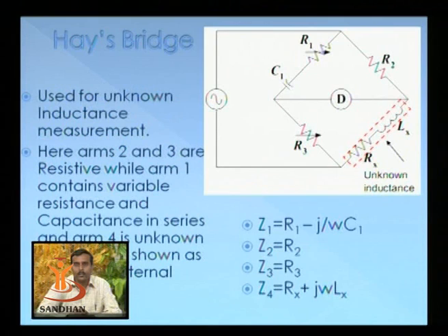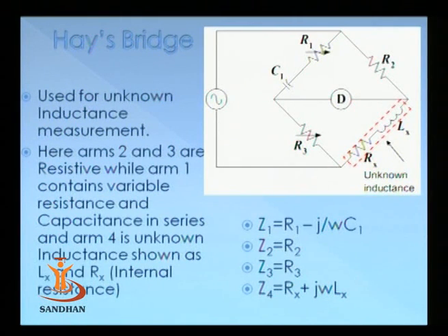Going back to the circuit, now here we have placed resistor R1 and C1 in series. So this is going to give you a phase difference. If you are interested in having a very high Q coil, the phase difference required should be very small. So this makes the requirement of R1 to be 0.